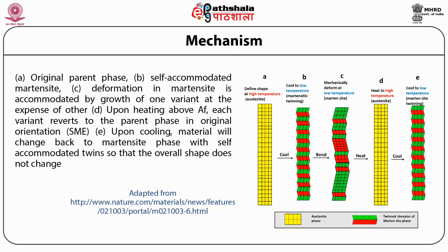This has been shown in figure D. Upon cooling again, the material will change back to Martensite phase with self-accommodated twins, so that overall the shape does not change.